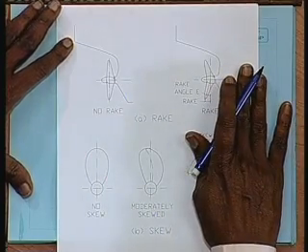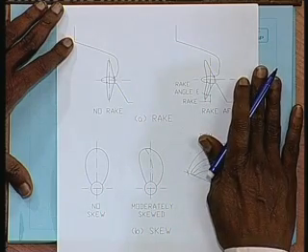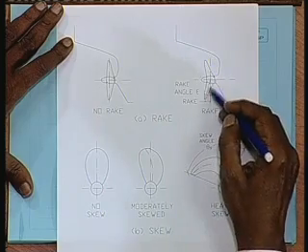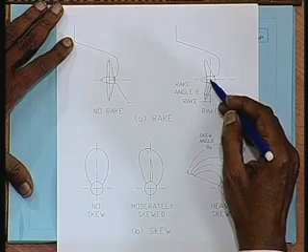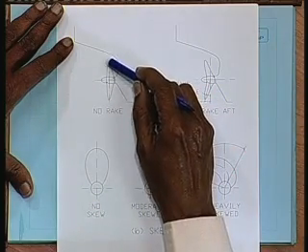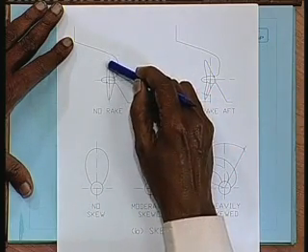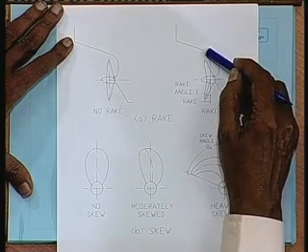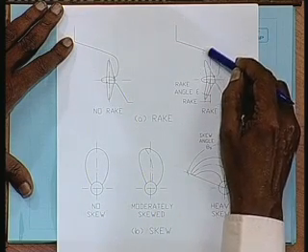Can you see it? Is it understandable? Can you understand? Right. What benefit do we get if I rake the propeller? You can see this distance between the propeller tip and the hull here is less than the distance between the propeller tip and the hull here.